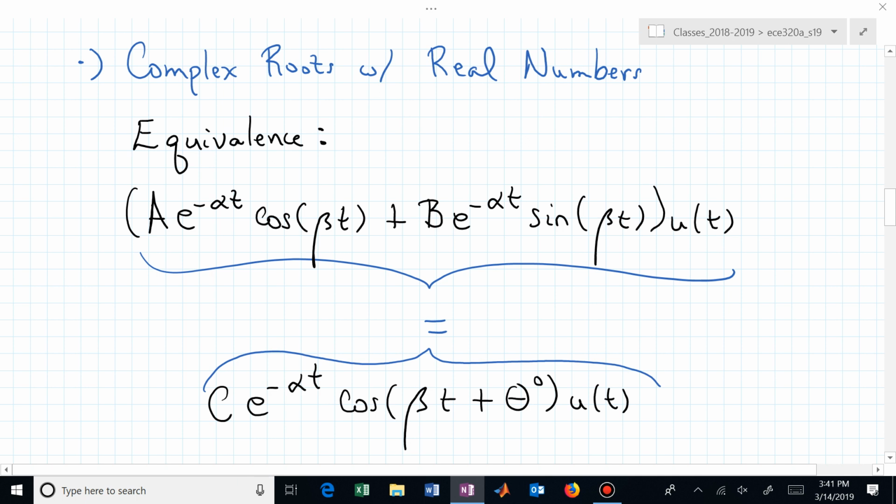What does change is now we've collapsed a sine and cosine that's damped the same and at the same frequency into just one cosine. Or you could have done it into a sine, but the convention is let's just work with cosines. And this is just a phase shifted, and you could just think of that as having a time lag or a time advance. That's what a phase shift really corresponds to, if we were to factor this beta out of that angle.